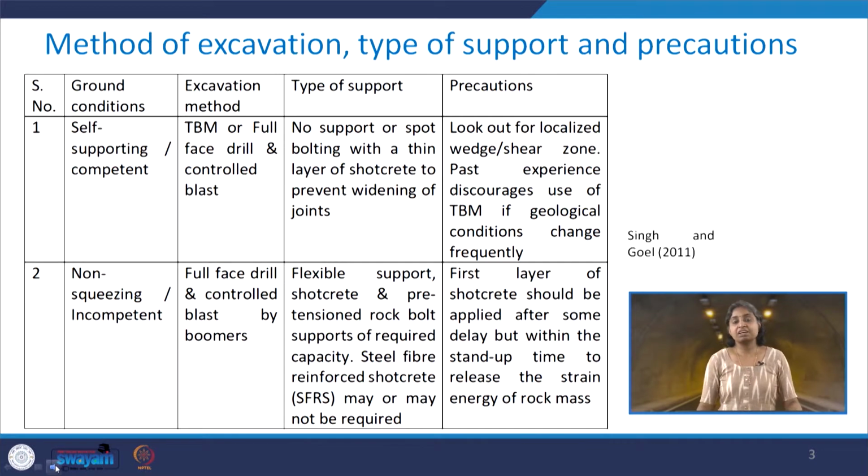Coming to the various methods of excavation, type of support and precautions corresponding to every ground condition. These ground conditions and the typical behavior of the rock mass corresponding to a particular type of ground condition we saw in the previous class.